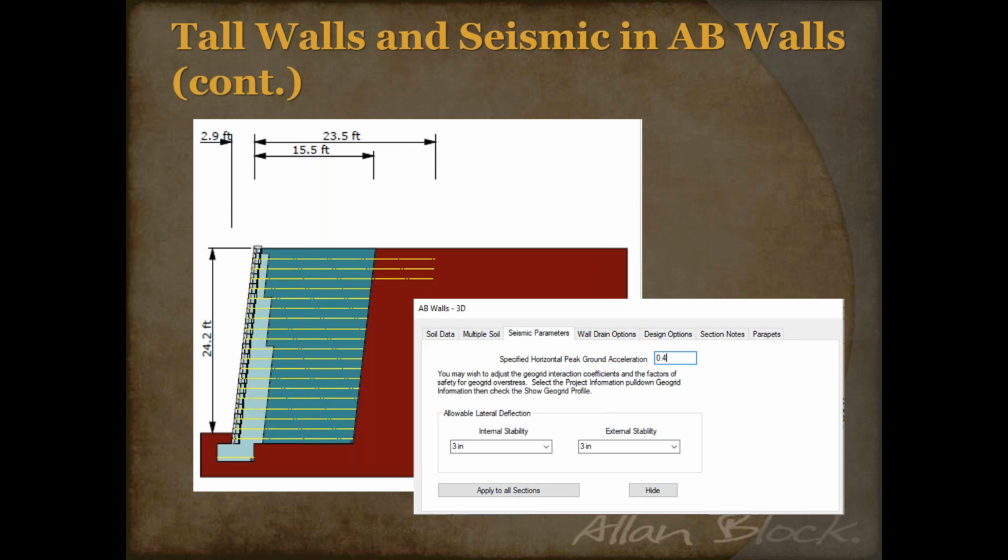Another thing to point out here, I think I was running this one with pretty poor soils, but you can see our base size was increased pretty significantly actually from that 6 inches by 24 inches. Now it's a very large base. That may or may not be necessary, but you'll see that happen if you have seismic turned on and you're running poor soils. It is a good thing to increase the base size in a lot of applications. This might be a little excessive, so if you ever see that happen and you can't change your parameters to get it to go away, you can always reach out to us and talk to us about that to see if we think it is actually that large of a concern, because typically soils that are poor like clay are going to have cohesion and that sort of thing, which would eliminate that large base.